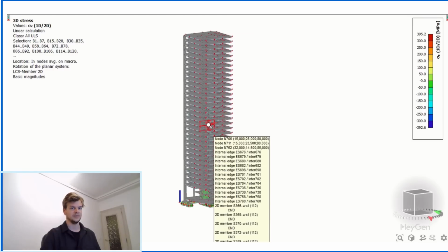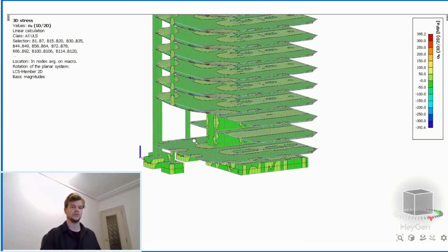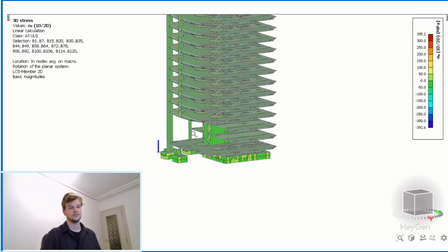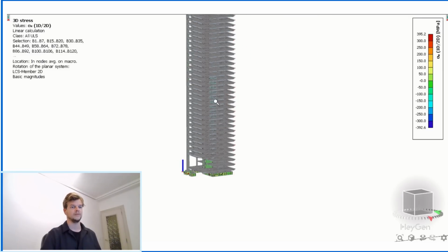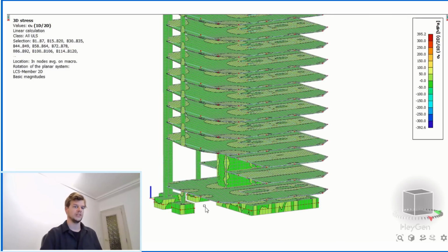To test the collapse mechanism, I removed the 2 front columns, the same ones that failed first in the real footage. The result? The structure can't redistribute the load. The stress in the remaining elements jumps now also from 20 MPa to over 60 MPa.